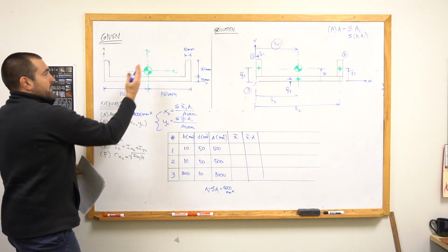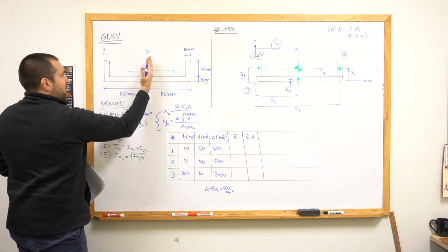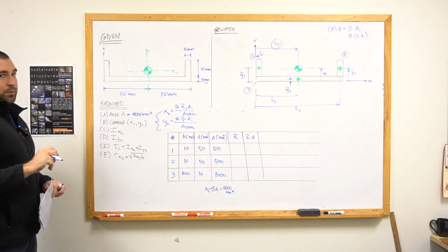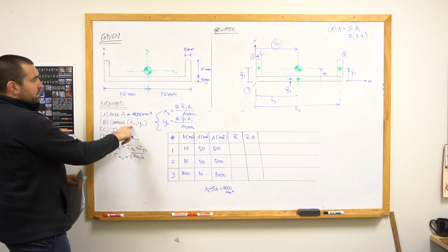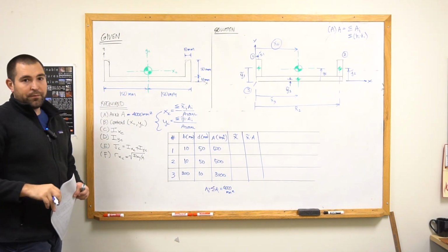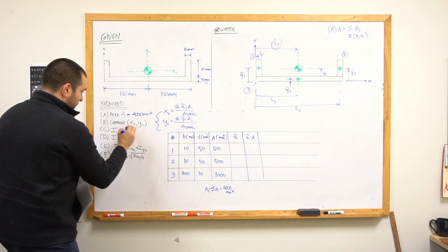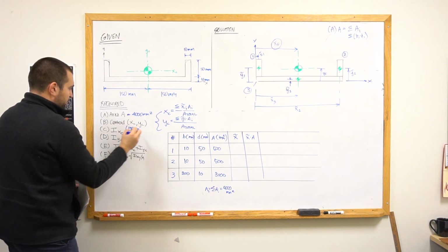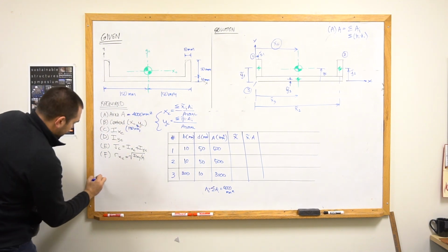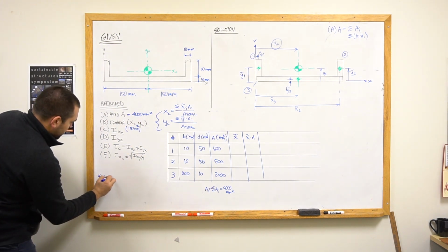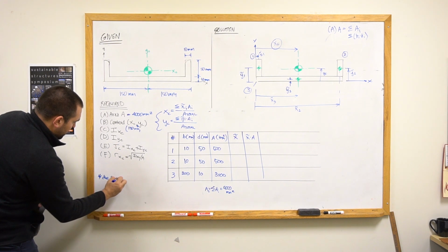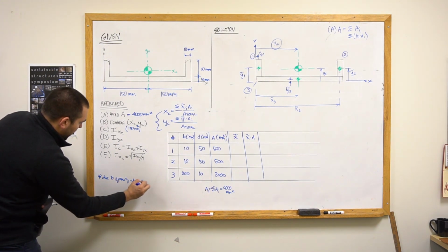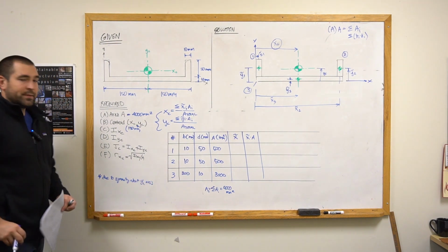So here, this is a symmetric shape about the vertical axis, and so I can simply write down, due to symmetry, x sub c simply equals 150 millimeters. And so 150 millimeters, and I'll just put a star right there, and down below I will say due to symmetry about y sub c axis.